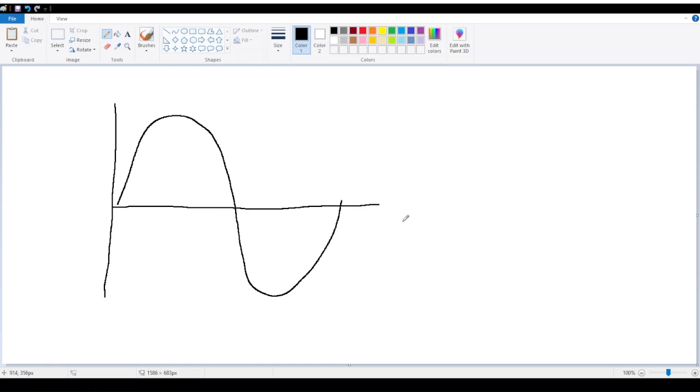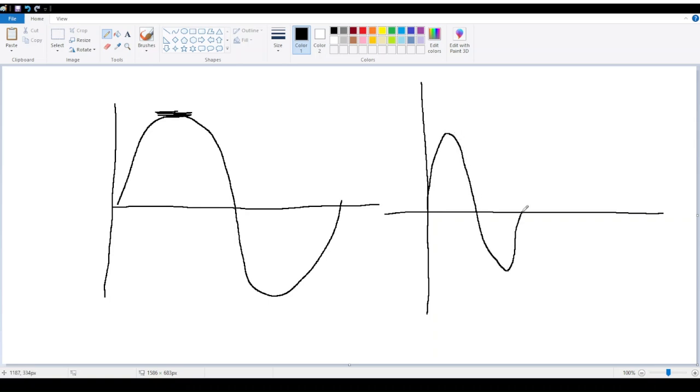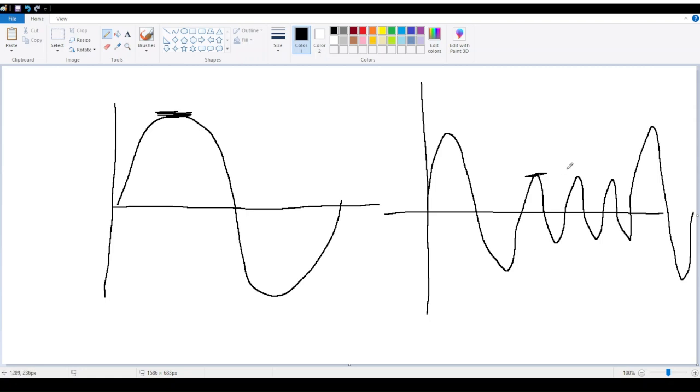And essentially with the first method of closed loop control, which I think is the easier method, we're going to be trying to track this peak from cycle to cycle. This peak, that's all we're going to be sensing in the code. Well, there's actually a way to do it in hardware. Obviously, you could use a rectifier and a capacitor, and automatically that gives you the peak. But it's important to note that if you're using this particular sensing method, it's quite slow. So essentially, we're just going to be sensing the peak, and then we adjust the amplitude modulation index. And so essentially what you'd expect to get would be something like this. So sense the peak, and then it goes down to the particular value that we want. Although if the set point is a little higher, it goes up like that. But essentially all the time we're sensing that. We're always sensing the peak.